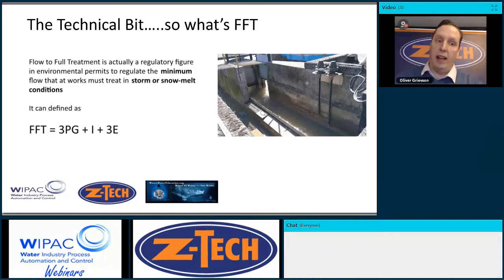So, flow to full treatment, and here we have a picture of quite a nice storm split. It's actually a regulatory figure, and I remember on the Flow TAF group there was a lot of arguments over what was flow to full treatment, what was pass forward flow, but I think a safe way to define it is it's a regulatory figure. It's in the environmental permit. It's an instantaneous flow, but it's the minimum flow that a treatment works must treat before going to storm.